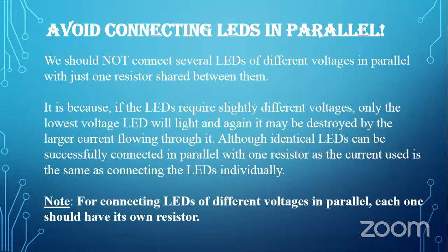Although identical LEDs can be successfully connected in parallel with just one resistor, as the current used is the same as connecting the LEDs individually. Note that for connecting LEDs of different voltages in parallel, each one should have its own resistor.